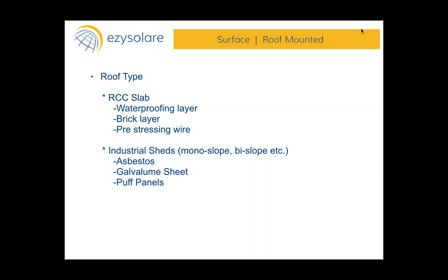In lieu of that, you can use pre-casted concrete blocks. So you're saying we bring all the aggregate to the roof, and then we cast it there, and that's called in situ. Right. Is in situ a very popular way of doing rooftop structures nowadays? It is pretty popular in India, because the kinds of structures we use today are not inclined towards ballasted structures, and we'll explain how the cost economics work around them. Currently, the structures available in the market are more inclined towards in situ casting.